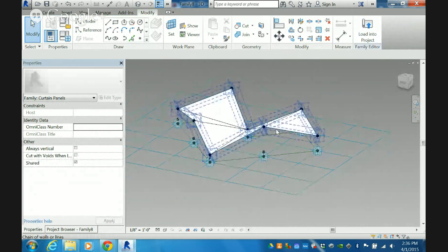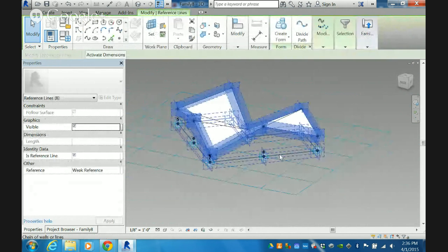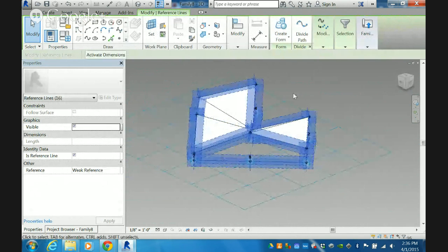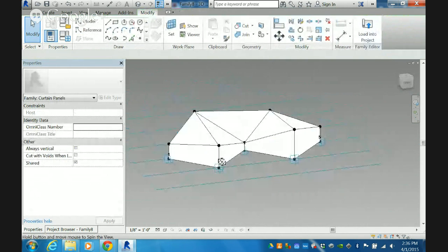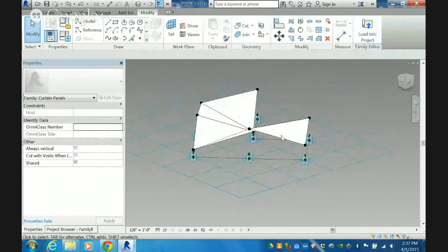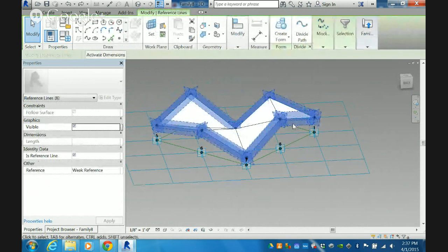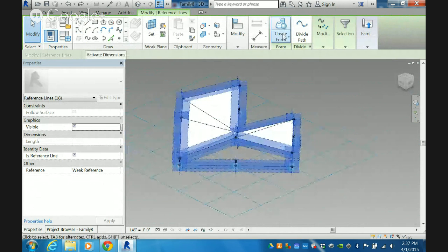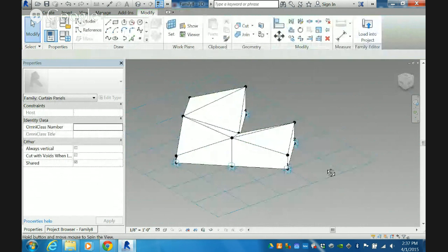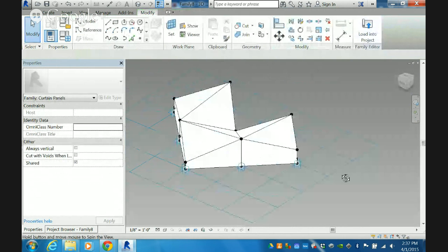And while we're at it, let's also do something. I'm just going to test something here real fast and just see if this is going to work for us. Okay, that worked out fine. So all I did, because I want this thing to be kind of like this weird extruded block that we can work with. Everything should be chained together from those lines we just created that surface. If you select that chain of lines and the chain below, just get those two guys selected and do create form. It'll finish and box it out the rest of the way for us.